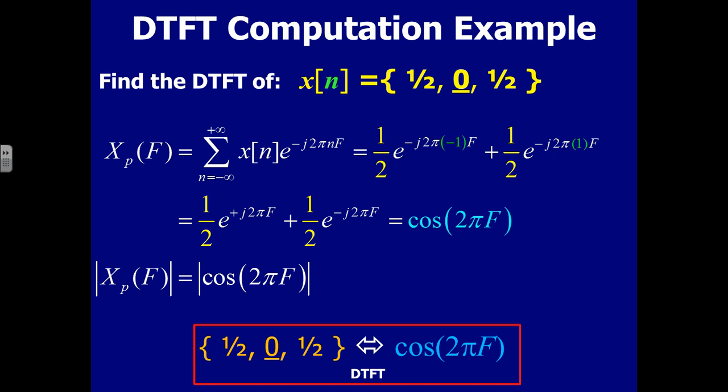If we cast it into our normal way of describing transforms, breaking them up into magnitude and phase pieces, we would plot the magnitude of the cosine function, which does go negative at times, and so that would be a different function than just the pure cosine 2 pi f. The phase angle then, it's a real function, but the phase is not technically 0 everywhere. Anywhere that cosine function gives us back a negative value, I would have to account for that by applying 180 degrees of phase. In terms of radians, it would be a plus or minus pi radians of phase.